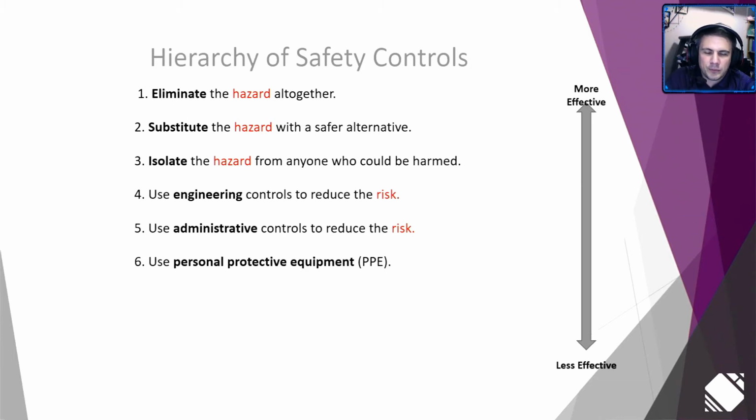Well, that's really not the right way to do things. Move that control by design down to the ground level so that they don't have to go up on an elevated platform. Alternatively, lift the poles higher so that the voltage is much further away from any risk. Just keep that hazard away from anyone that could be harmed.